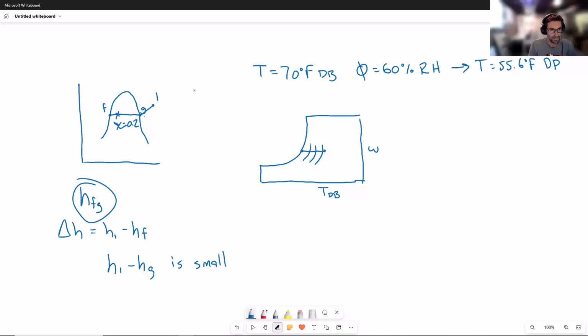And that's really what this problem is about: preventing condensation from forming on the glass. So the inside surface temperature of that glass cannot be allowed to get any colder than this. And so we can start the problem by making the statement that if this is the heat flux, we're going to do hA delta T, and then the area was not given. So instead of doing total heat transfer, we're going to divide by area on both sides, which we show in the solution. So the rate of heat transfer per unit area, little q dot, the heat flux, is going to be h times delta T.